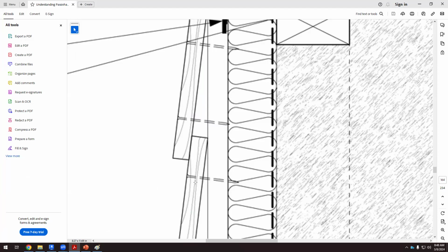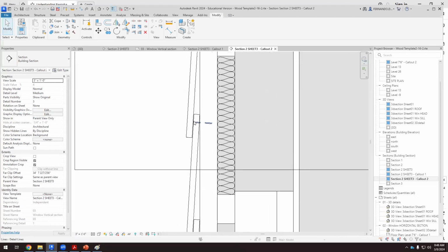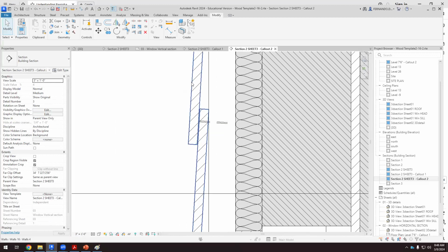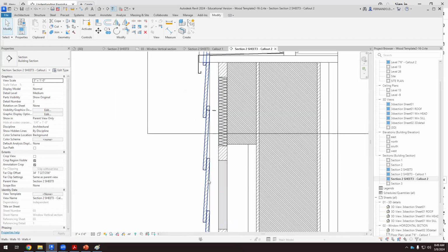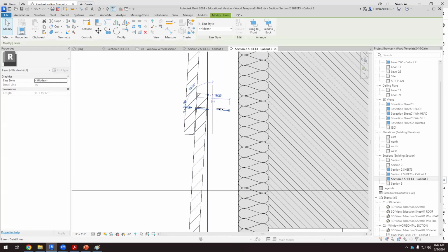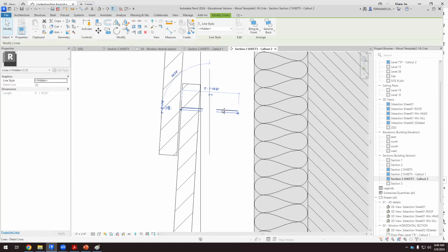A nail can be made of steel, even if it's stainless steel. It can be affected by water, and we can have corrosion here. So that's why I want to nail this here, and then the following siding will be hiding the head of that nail. Okay, so that's what I would do, yeah, I think this is better.